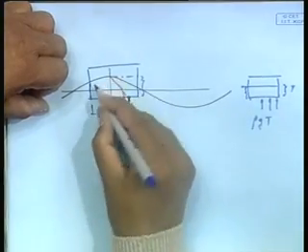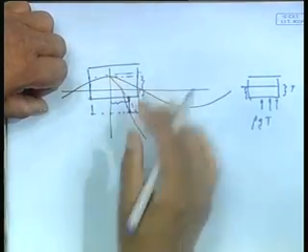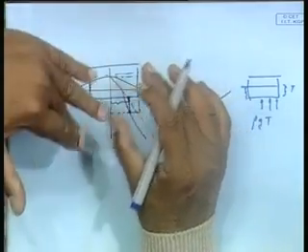which means the body must actually come down, because the pressure below the crest has reduced rather than increased. So therefore the ship must come down further in order to support itself. Okay, and the opposite would actually happen in trough. So therefore what would happen, of course this actually happened in a very small, the numbers are not so large, but there is a tendency for the draft to come down and go up more because of the hydrodynamic contribution, dynamic pressure contribution. So the dynamic pressure has therefore an extremely important role to play.